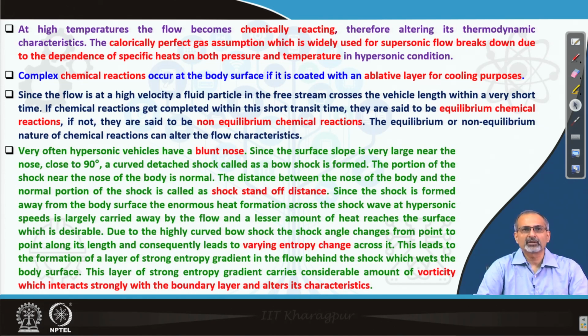Since the shock is formed away from the body surface, the enormous heat formation across the shock wave at hypersonic speeds is largely carried away by the flow, and a lesser amount of heat reaches the surface, which is desirable for protecting the surface.